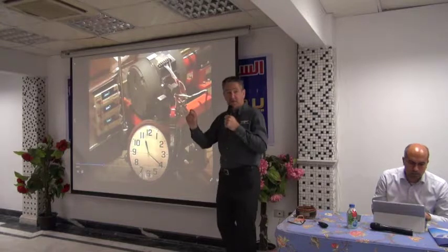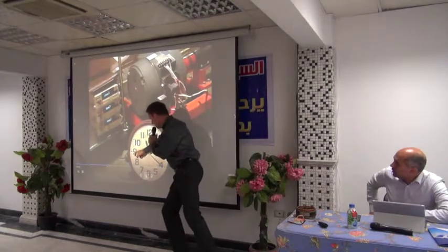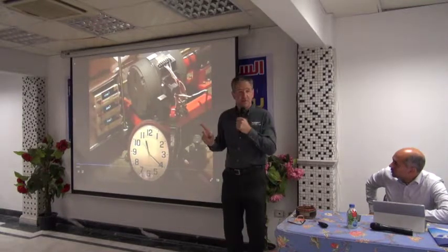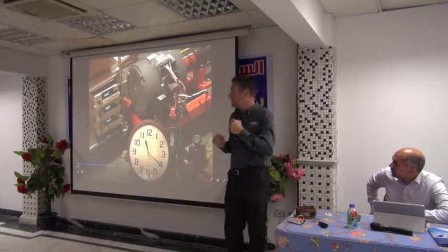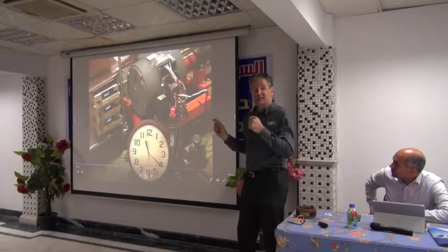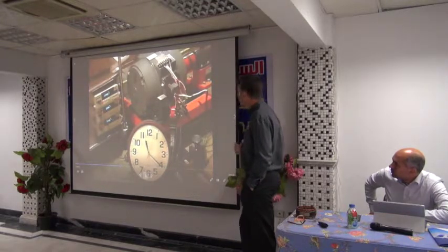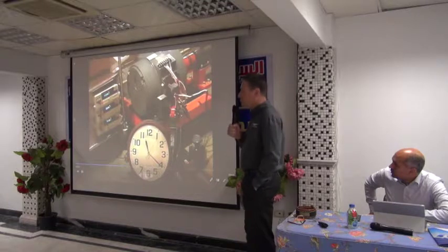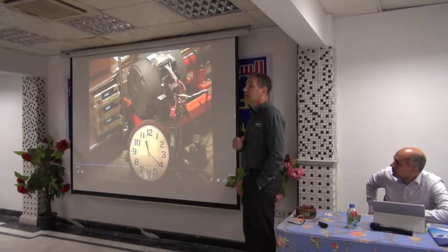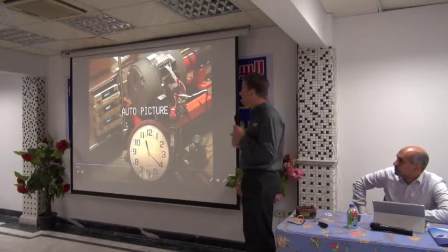Okay, so now there's a short circuit inside the motor. The time is here, 45 seconds. He says the currents are not showing the problem. There's a short circuit in the winding, the currents are still balanced. So this is a 100% load test. The three phases are balanced, even though there's a short circuit inside.